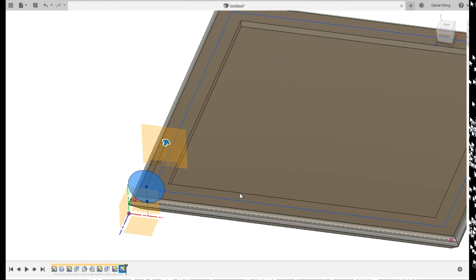Okay, and the reason why I've done that is now I can redefine the sketch to not be on the plane that we just drew, but on this new plane. Okay, so what I've done, just to show everybody again, is I've created an offset plane through construct. And reference geometry is very useful.